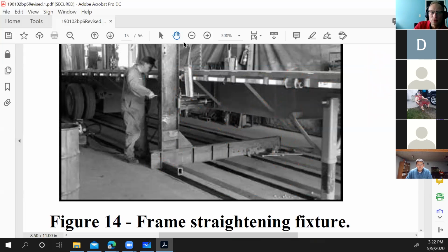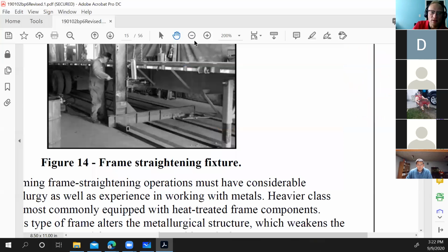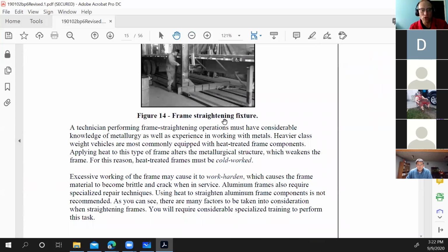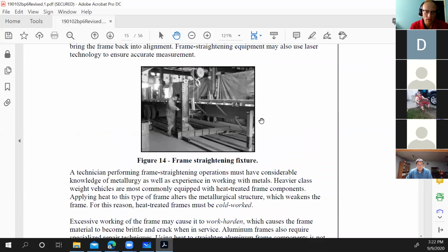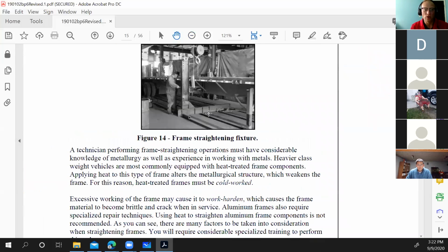You bet. So yet again, if you don't have these types of devices where you're working, you're probably not going to see this kind of stuff. You have to know how far you could bend something. If you've ever bent a spring steel, especially, and frames do have an amount of springiness to them, you have to bend it farther than where you want it to stop, essentially. And so there is a process involved with it.